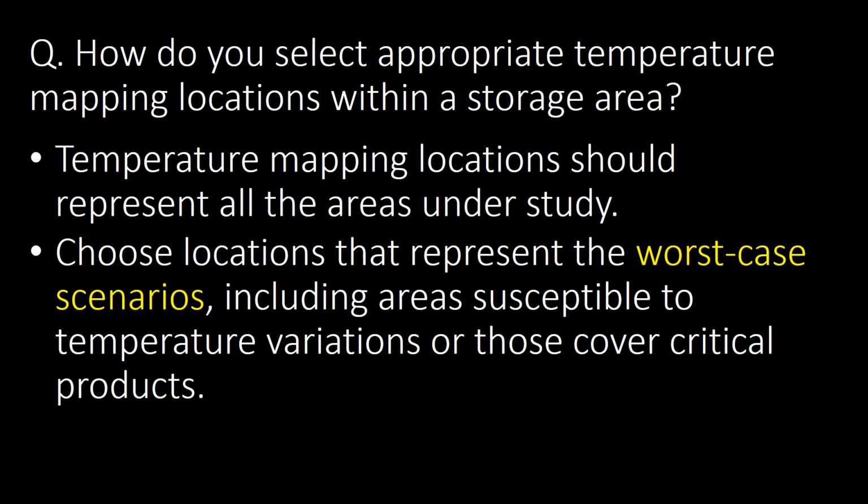This is a very important and frequently asked question: how do you select appropriate temperature mapping locations within a storage area? The very basic rationale behind selection of mapping locations is that they should represent all the area under study. Choose locations that represent the worst case scenario, including areas susceptible to or prone to temperature variations or those which cover critical products.